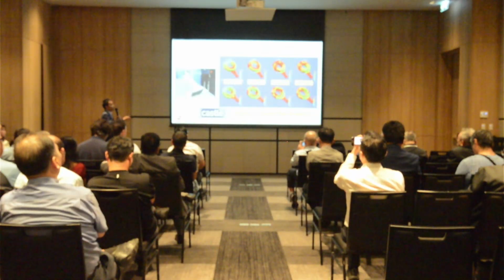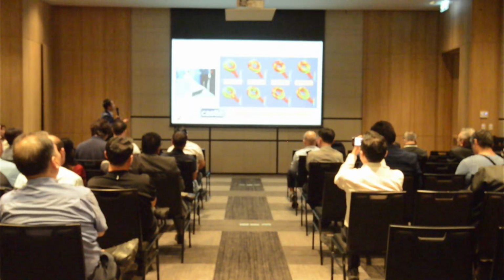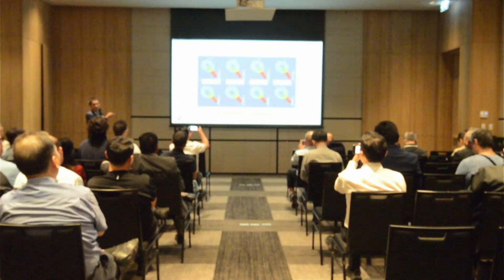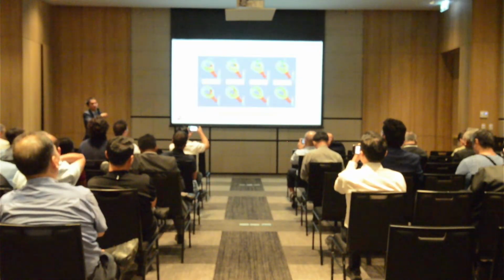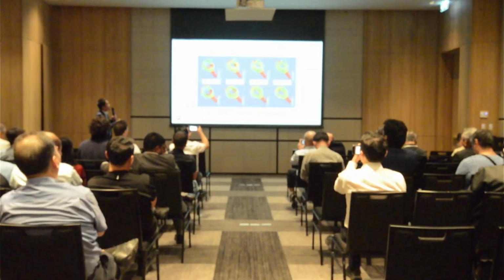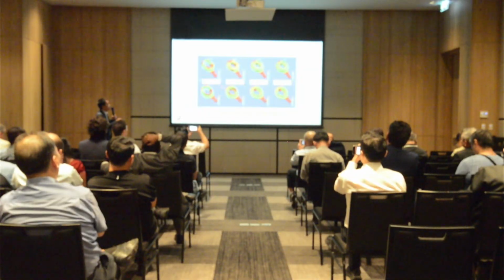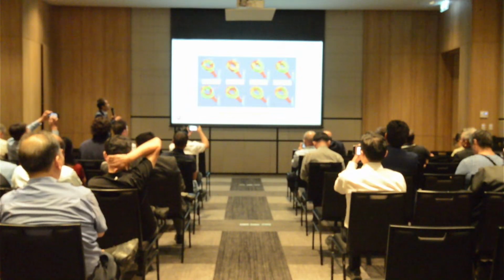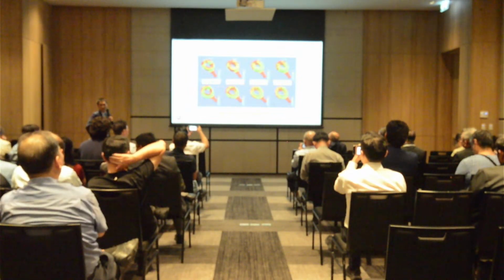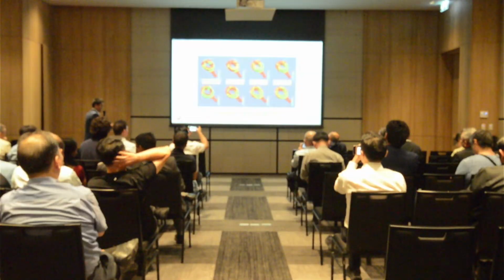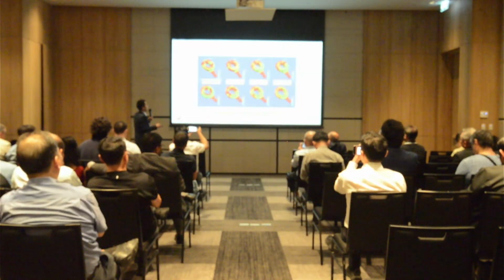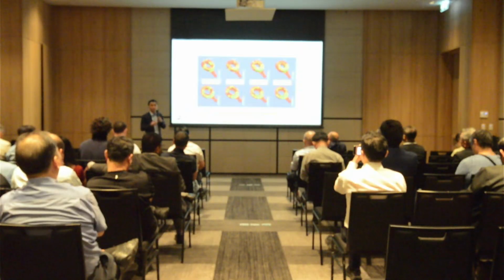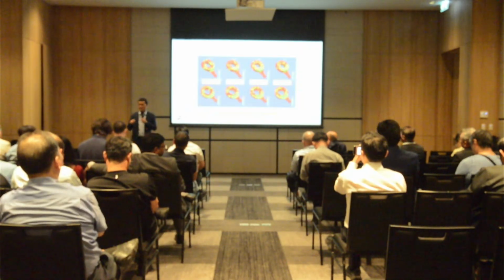Here not only is the viscosity different, we also try the gate velocity. If the gate velocity is 33 meters per second, it seems like normal die casting. Again, you can see the higher viscosity gives less turbulence, but you can still see entrapped air, so you need gating here and venting here. It's different. With higher viscosity and even higher gate velocity, we have less entrapped air. That's why we have a lower porosity level.